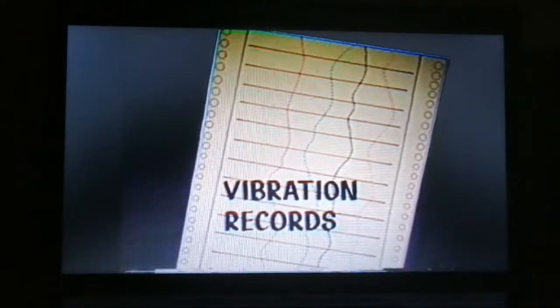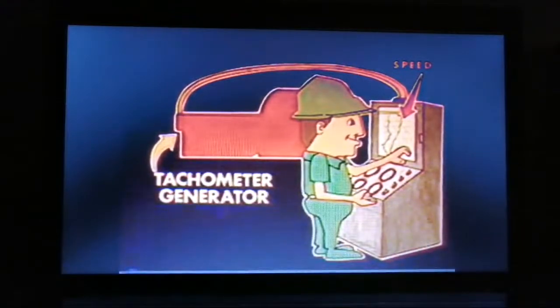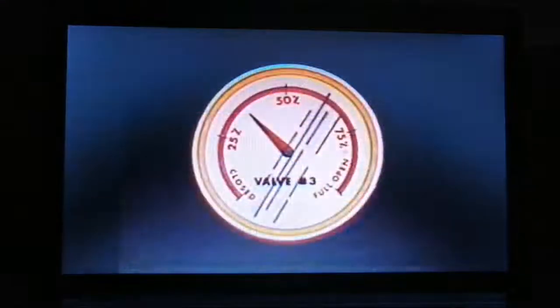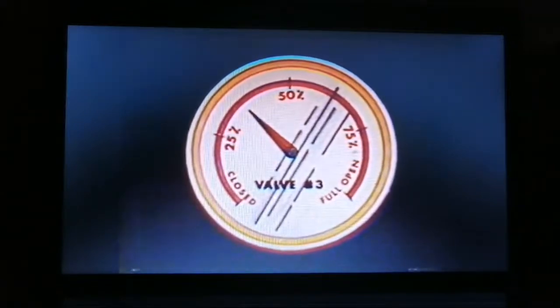Turbine vibration is often recorded, indicating the magnitude of vibration at each main bearing, often also indicating turbine speed. Rate of rotation, very important in turbine operation, is usually monitored by a device called a tachometer. This generates electrical voltage or pulses which increase with rotating shaft speed. Usually, along with the device to measure and record the turbine speed, recorders or other instruments will indicate position of the main steam valves.